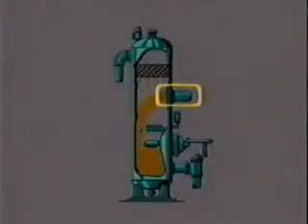A 2-phase vertical separator, like this one, is best suited for well streams with high liquid content and low gas volume. 2-phase vertical separators are typically used when the well stream contains large quantities of mud and sand. Easy cleaning and draining make it best for these applications. Here the well stream enters the vessel near the midpoint of the side.